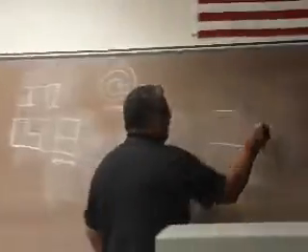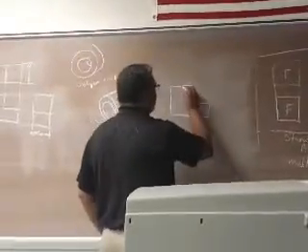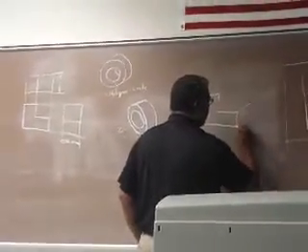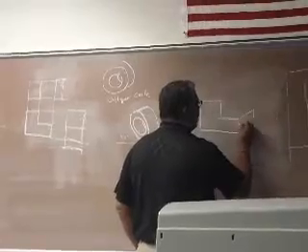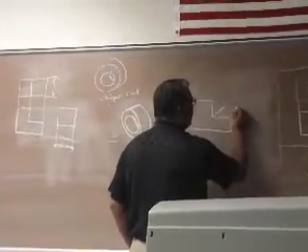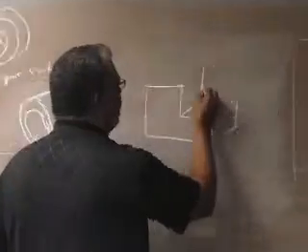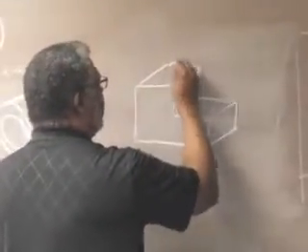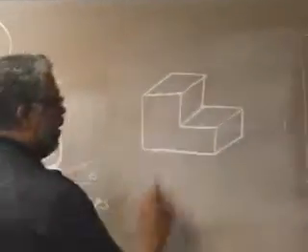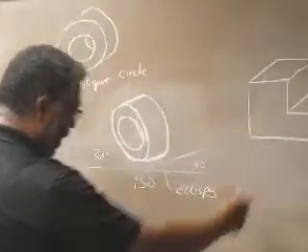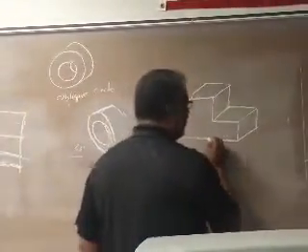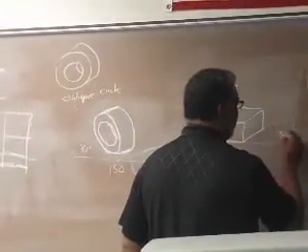So to show my depth here, whatever that distance is, and depending on what type of oblique I'm going to draw, I draw my lines that show my depth. My lines remain parallel. These remain parallel because they're parallel in the orthographic view. And then we got this here, and this remains parallel right there. That's my oblique of this drawing. Now, when I did this oblique, let's say we decided to go back 30 degrees.